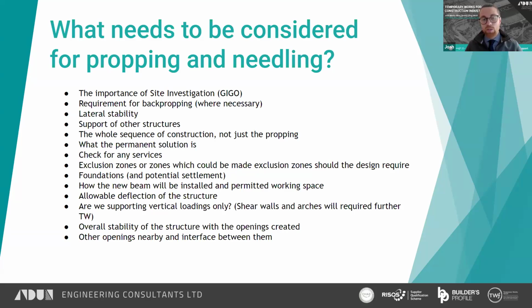And the other one is to do with load history. And this is a phenomenon that will include how to put the loading back into the permanent works once the propping has done its job. Another one is what the permanent works is going to look like. If we plan in advance and we understand what the permanent works is and how it interacts with the structure, then it may be that we can incorporate the temporary works into the permanent works and make a very slick and efficient and buildable solution and potentially eliminate any temporary works.